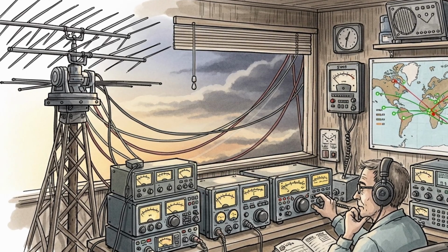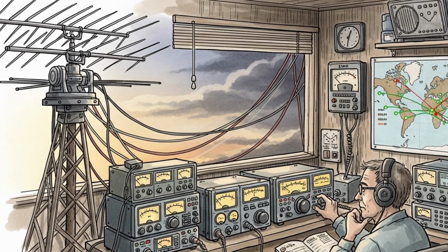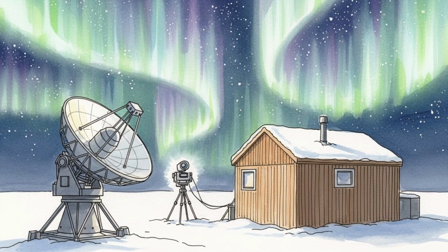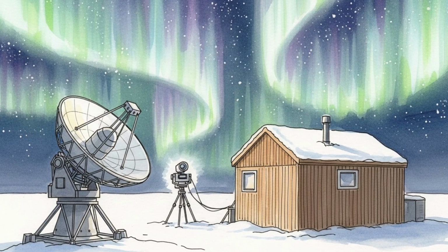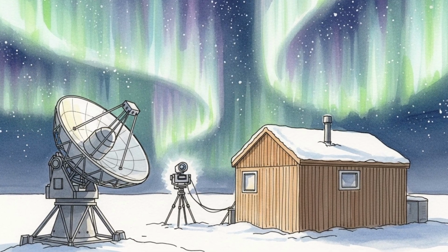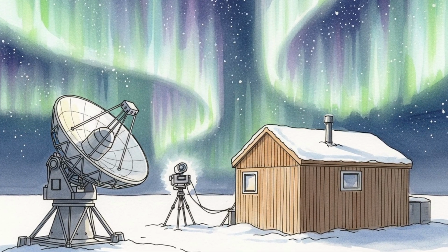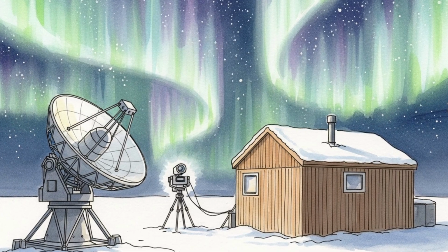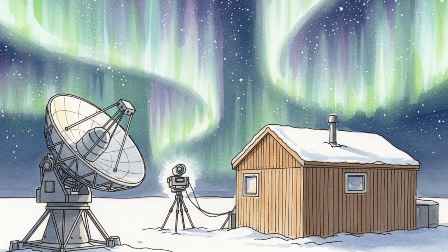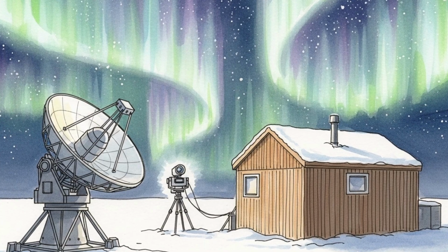System-level effects appear as reactive power swings and loss of voltage support. Generators reach field current limits. Automatic voltage regulators work harder and may lower stability margins. If reactive reserves are not available, undervoltage spreads and forces load shedding or trips.